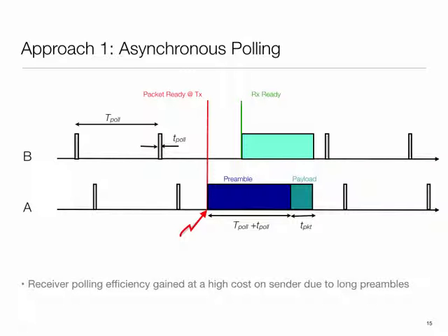Okay. So what you're saying is I can have something which only detects RF energy. The problem is there are all sorts of sources of RF energy. So that can falsely wake you up. So what you are describing is what I was talking about a few moments ago, which is the wake up radio concept. The very simple wake up radio just monitors the RF band where you expect a transmission, and the moment it sees RF energy, it says, aha, someone is trying to send something, I'm going to wake up. The problem is there is too much spurious RF stuff, because remember, a lot of these things are operating in unlicensed bands. Your microwave oven starts, bang, all the sensors are going to wake up.